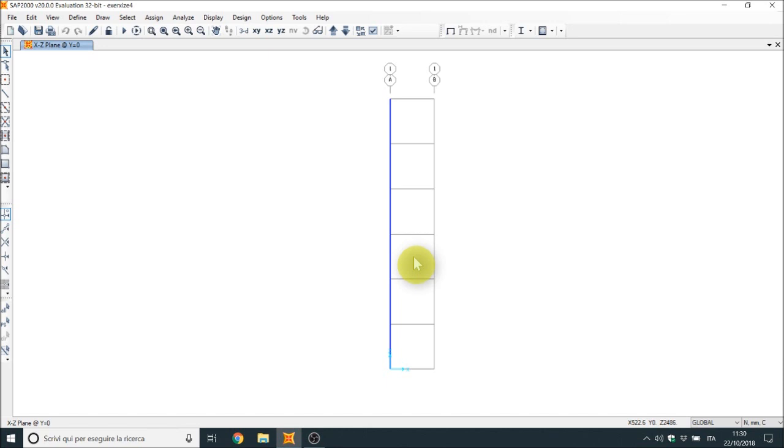Now we can just use the buckling analysis. If you want to be sure and you want to stay on the safe side, the useful thing is to perform a second order analysis, and instead of using the L as the geometrical length, using the L depending on the buckling factor.